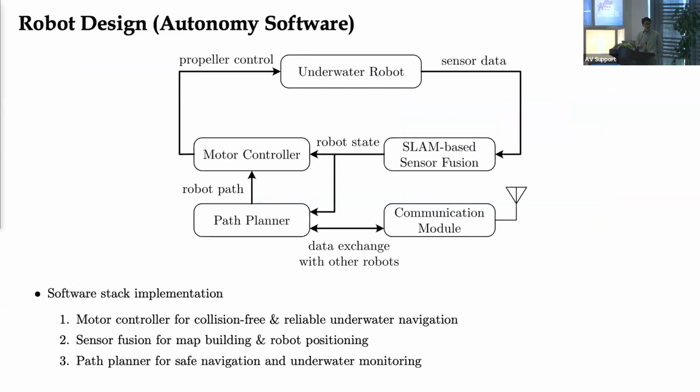We spent a lot of time thinking about how we can nicely build a feedback loop around individual robots. Here, we actually have two feedback loops. One is around the robot, the sensor fusion and the controller. The other is between the robots. If they are sharing information through the communication channel, that forms another, occasional feedback loop between the multiple robots.